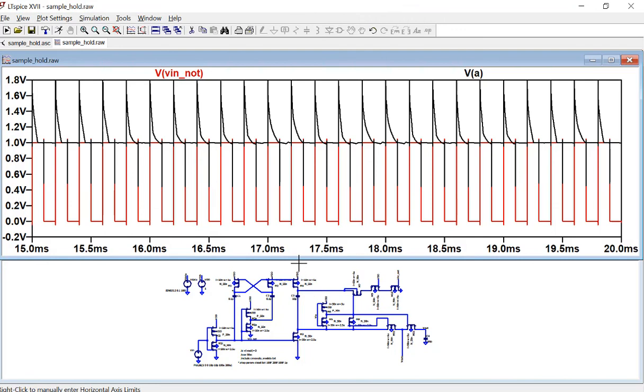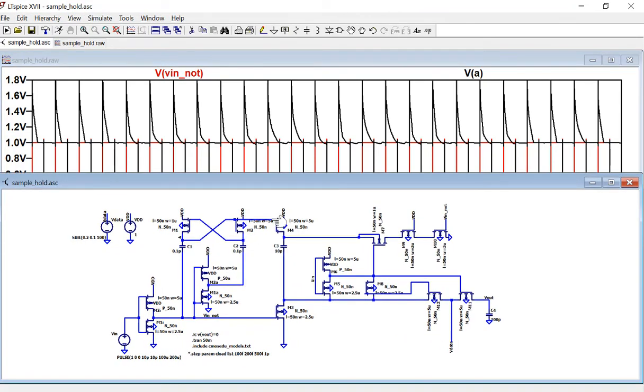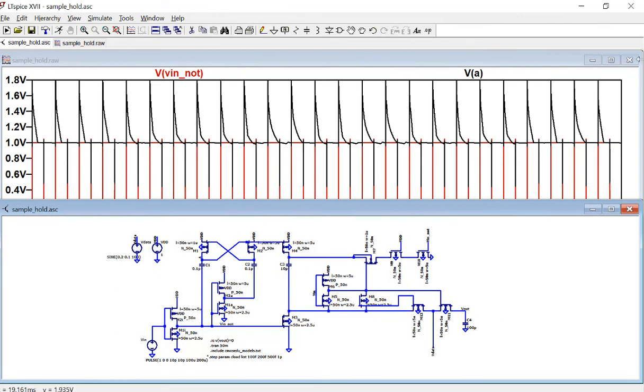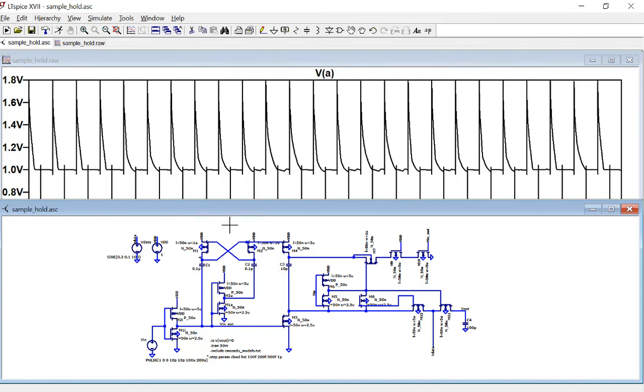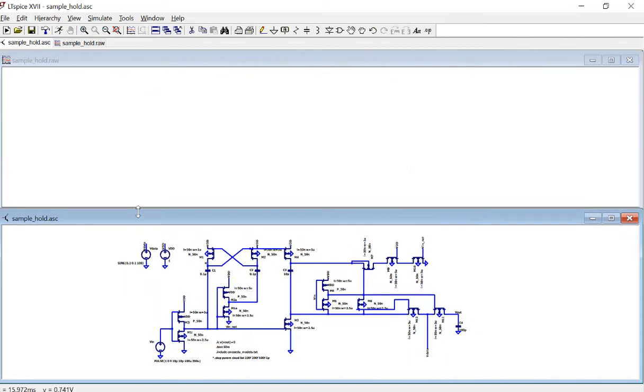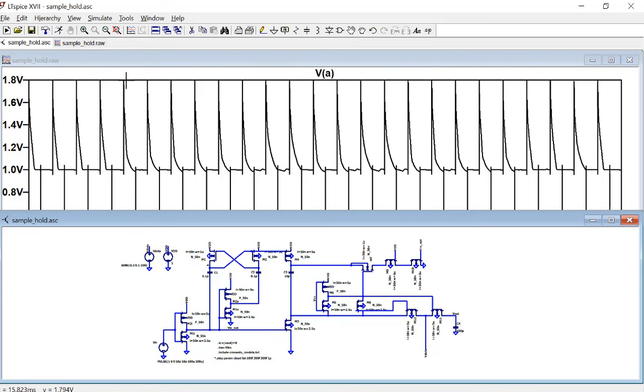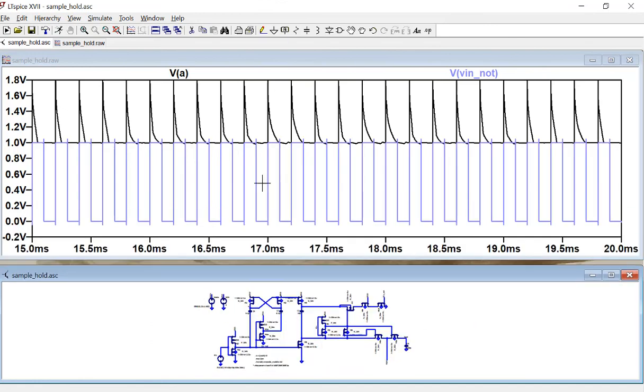All right, let's look at the simulation. I probed this point, right? So here the voltage is being boosted to somewhere around 2 VDD, which is somewhere around 2 volts, and then comes back to 1 volt, which is VDD. And what about the clock signal? So I'm going to probe this point here. And now let's see if this is making sense or not.